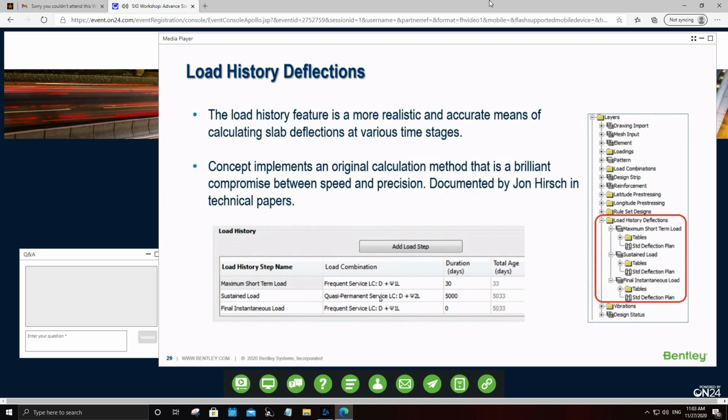You perform a design by the program and change all those program reinforcements to user reinforcements. Once you change those to user reinforcements, you're considering the full length of the rebars that has been designed by the program, including the anchorages and the development lengths, which probably help in reducing the crack width and also the effects due to the sustained loading.